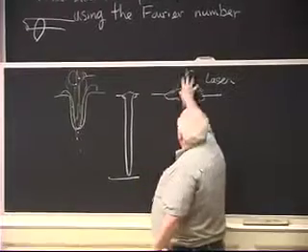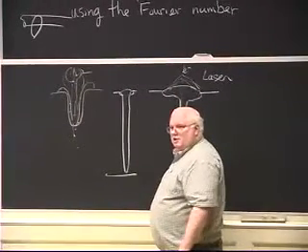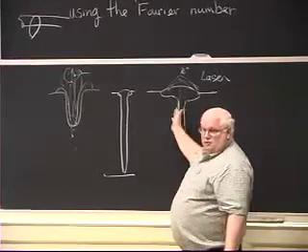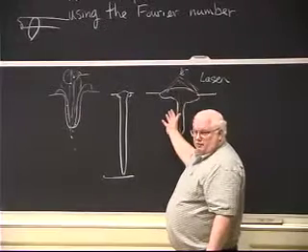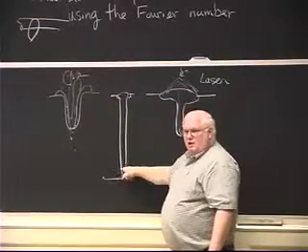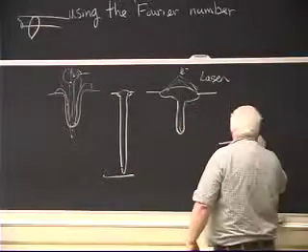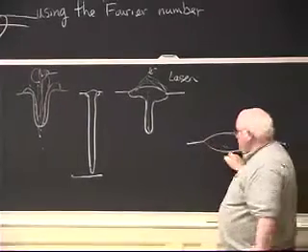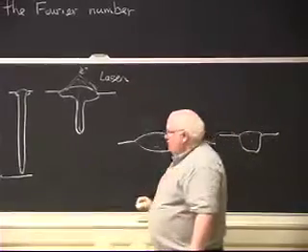Part of my heat becomes a diffuse heat source, and part of my heat source becomes a deep penetrating heat source. And in fact, to a first approximation, you can look at the shape of that weld pool and say, that's the shape of my heat distribution on the surface, okay? When I have a heat distribution that's a nice focused line, I'll get an electron beam that looks like this. If I am doing arc welding and I get a very broad, narrow pool, that's sort of the shape of my heat source. If I get a deep penetrating pool like that, I have a more intense heat source.